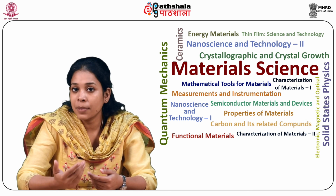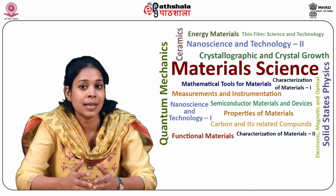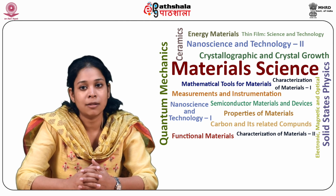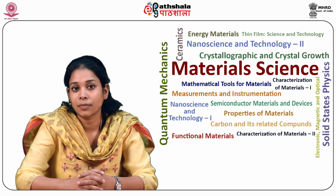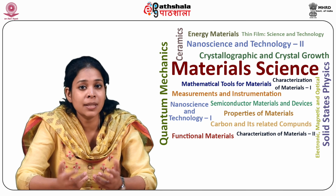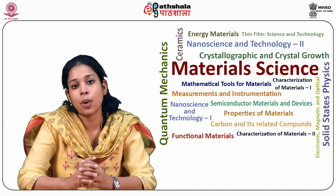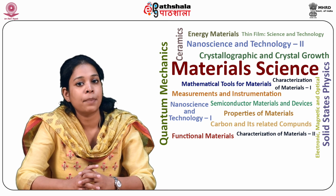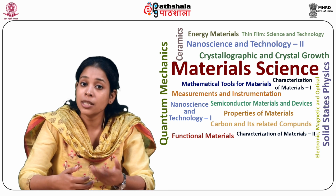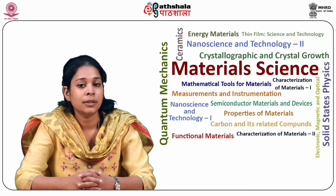The tribological applications of alumina are most important, and these include thread guides in the textile industry, spray nozzles for sand and hot blasting, rollers and other supports for the paper industry. Some of the other applications are extrusion dies, automobile pump seals and seals between parts which turn or slide with respect to one another. Alumina also has application in cutting tools, as shielding material in bulletproof jackets, as protective coating for helicopters and tanks, as well as bioinert material.